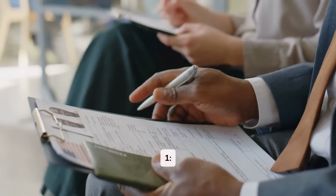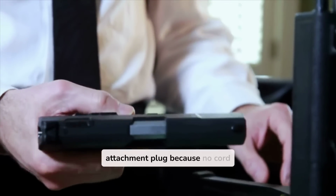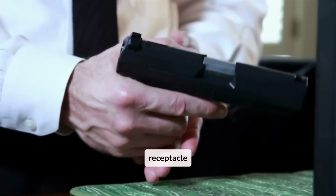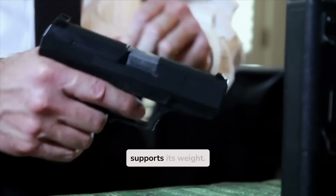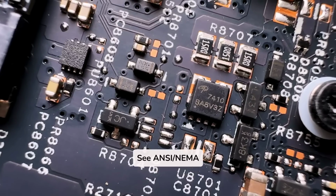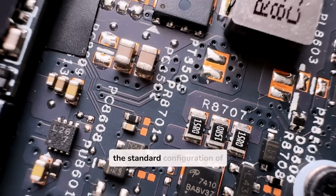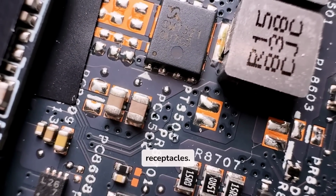Informational note number 1. A weight-supporting attachment fitting is different from an attachment plug because no cord is associated with the fitting. A weight-supporting attachment fitting in combination with a weight-supporting sealing receptacle secures the associated utilization equipment in place and supports its weight. Informational note number 2. See ANSI NEMA WD 6, American National Standard for Wiring Devices, Dimensional Specifications for the standard configuration of weight-supporting attachment fittings and related weight-supporting sealing receptacles.